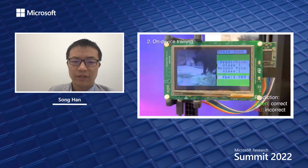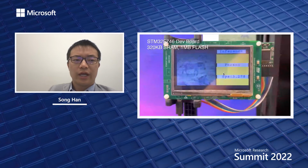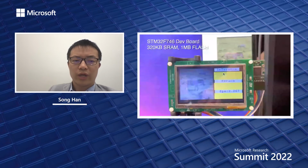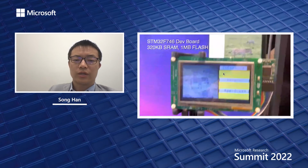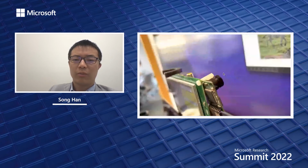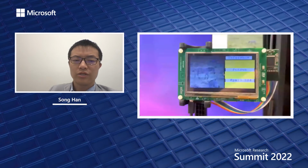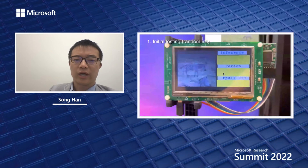And finally, we have a demo showing that we can actually achieve on-device training on this microcontroller that has only 320 kilobytes of SRAM and only 1 megabyte of flash. Initially, the model is randomly initialized. We have a microcontroller with a camera pointing to an image. Initially, it's wrong, classifying the zebra as a person.